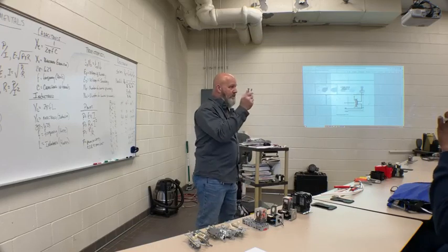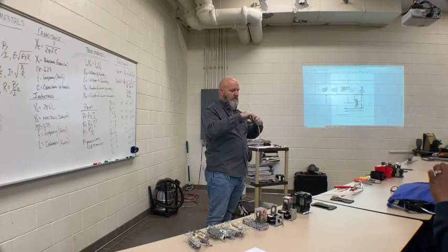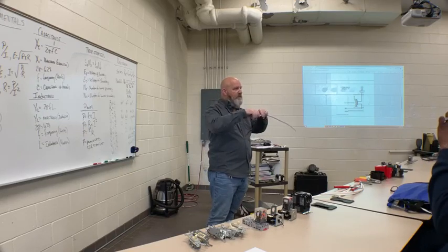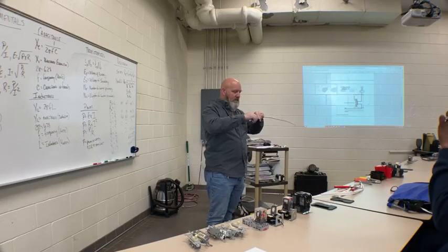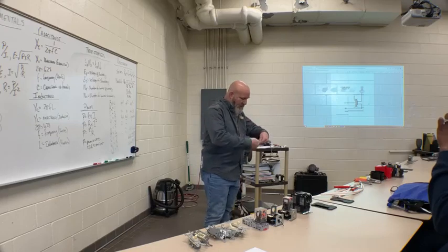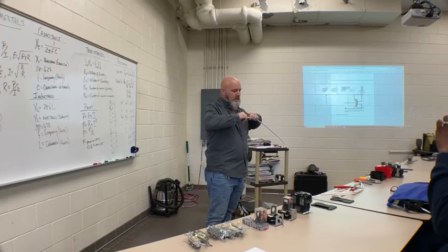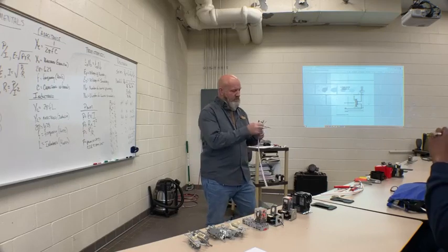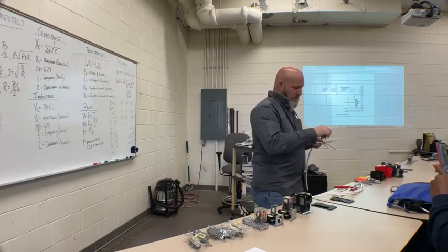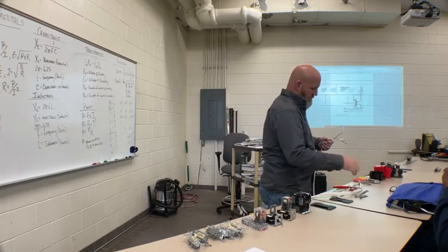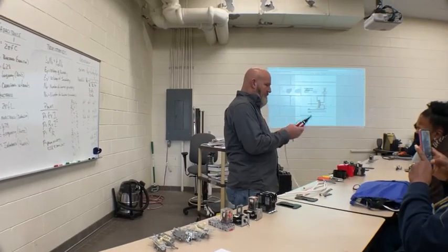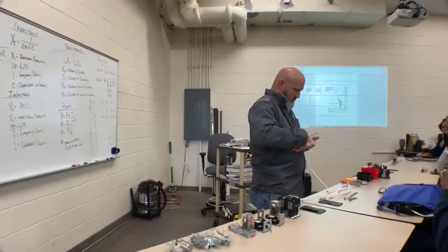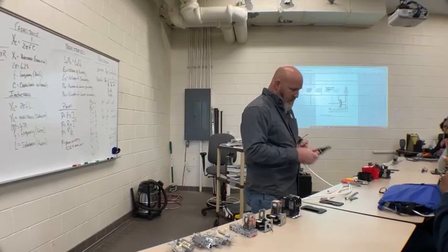I'm sure that somebody's got a lawsuit against this company because you can put your finger in there and squeeze it. They don't make these anymore. These are about as old as I am, probably. So you see that little blade in there, you push it down, and you pull back, and it takes the outer sheath off. Well, these are insulated. The ground is always going to be bare in building wire. And you would cut that off.